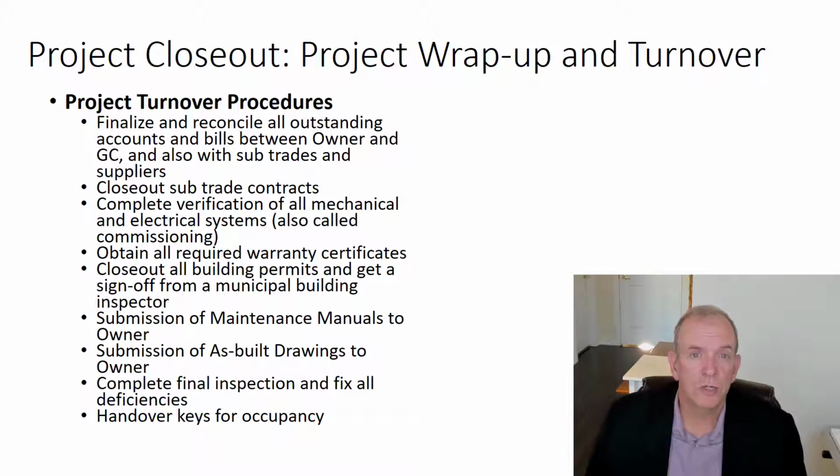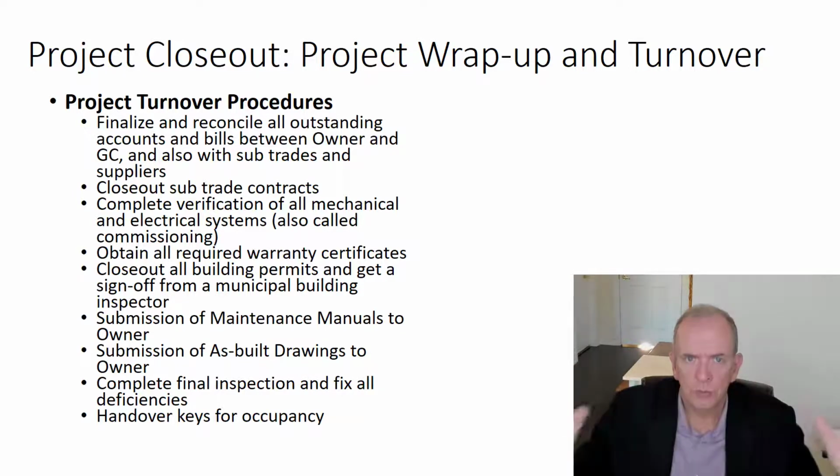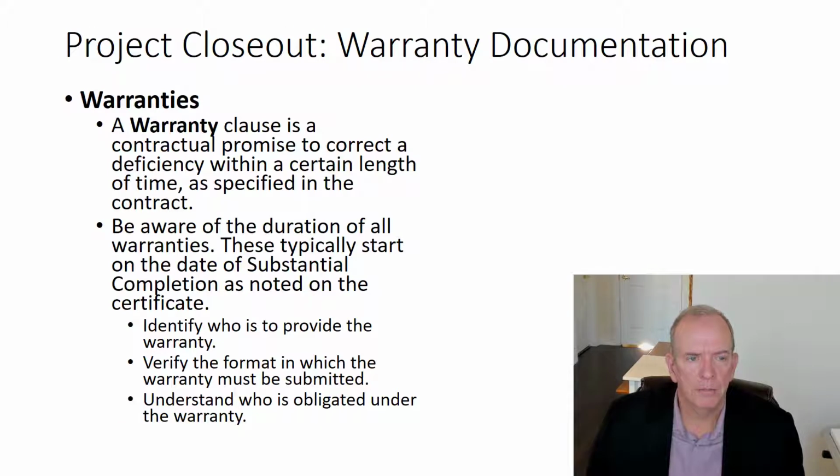And as-built drawings are a lot more complex today, especially if it's following a BIM model. The building may be going to what we call 6D of BIM, where you're turning over the as-built database for the project. It's got a listing of all the components and parts, and it's in a database, and the 3D model has been updated. And that's that turnover process. So it's an important part of the project.